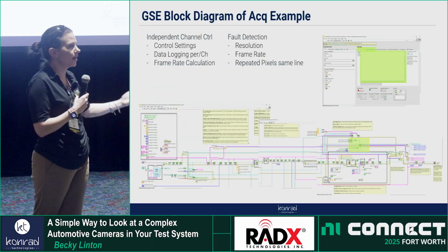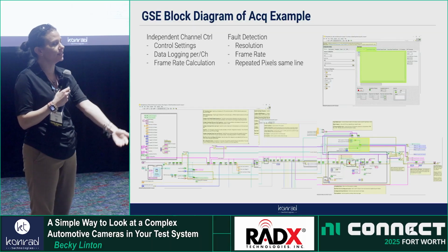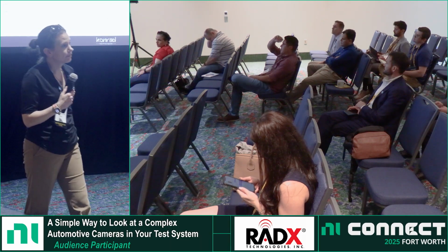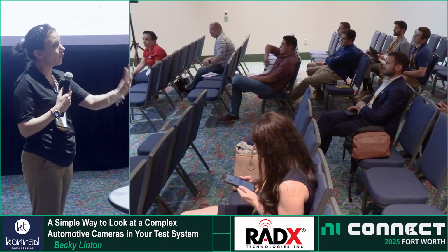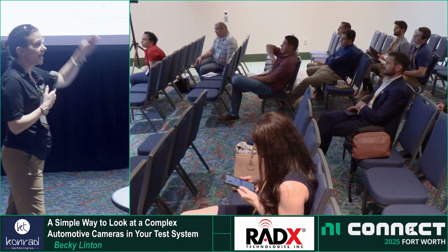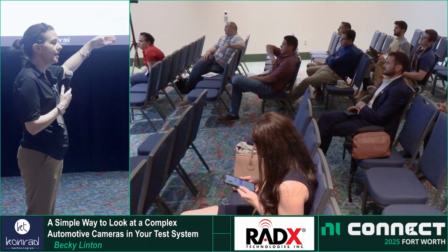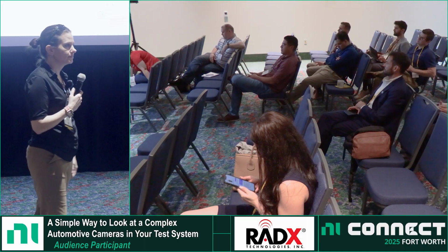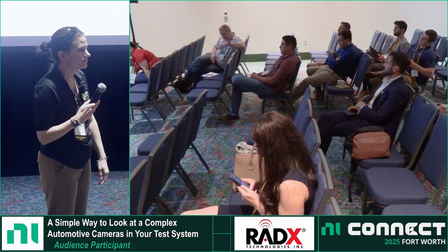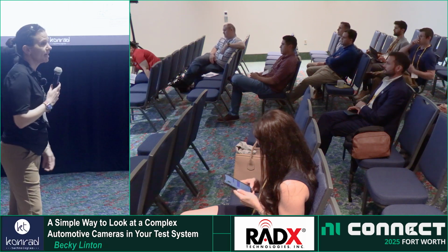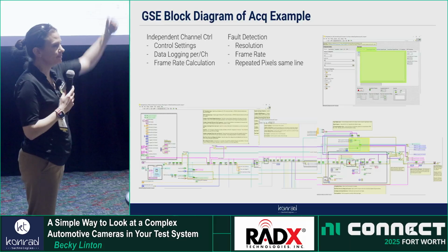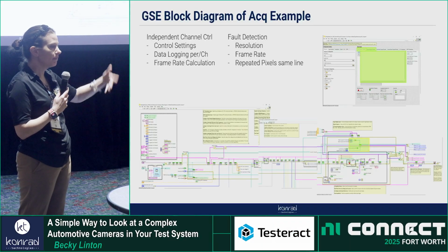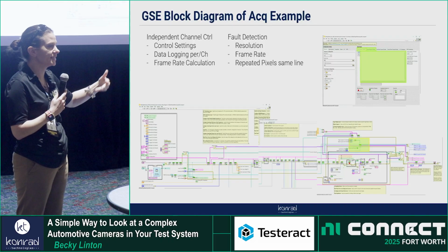Based on the camera, we send down the fault conditions, and then the FPGA reports back information. So you were using the same FPGA bit file to support the... We have 4 FPGA bit files, and based on what the customer picks for a camera, it deploys to the card. So then you can have a different API for each FPGA bit file, right? We don't have different APIs. We have the same top-level API. Okay, so the same top-level one that calls, and based on configurations, we load a different bit file. But because the interface on the bit file is the same, we were able to do that.